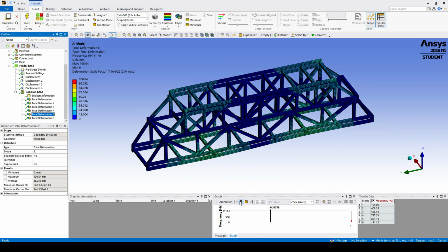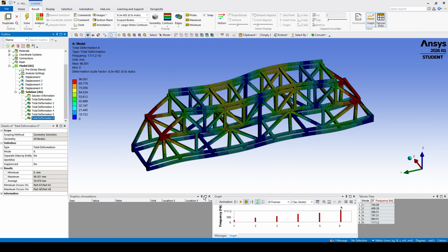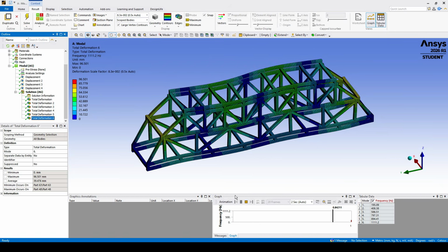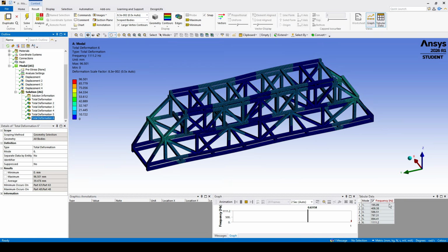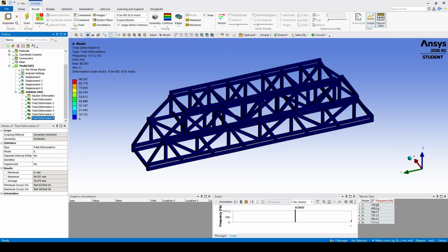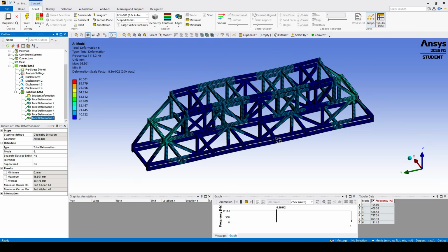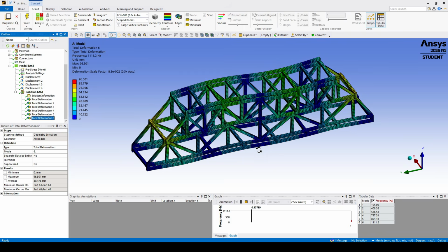And we have this mode shape, and the final one, the sixth mode shape, like this. So the frequencies, as we have there in hertz, are important themselves, but the mode shapes tell us exactly how the structure wants to move. So if a loading source excites one of these frequencies, the corresponding mode can become highly amplified.